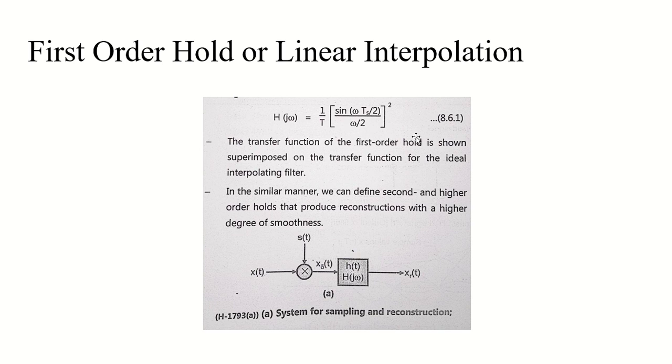The linear interpolation is what we choose, and as you can see here in this image, the reconstruction is continuous, although with discontinuous derivatives due to the changes in the slope at the sample points. We get rid of the discontinuities. The linear interpolation is sometimes called the first order hold, and it can also be viewed with the triangular impulse response h(t), right?